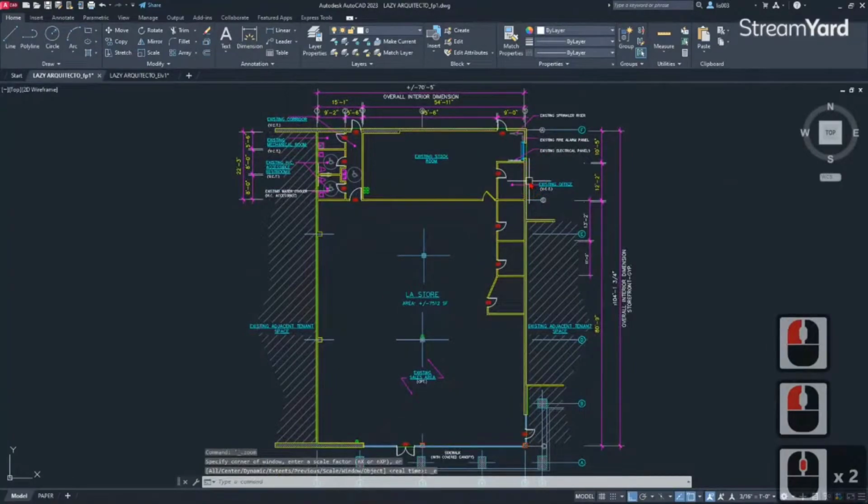All right, so that's a way for you to never create so many dimension styles. You don't have to do that. Only use this tip, which is setting up your dim scale according to the chart. So that way you only need one dimension style. All right. So let's go with the next tip.